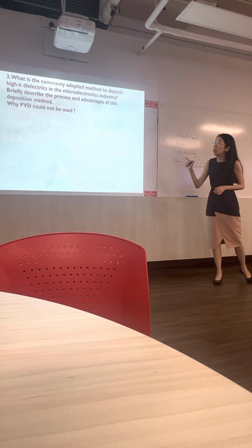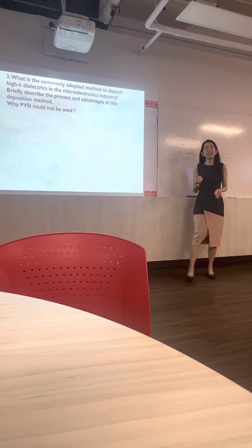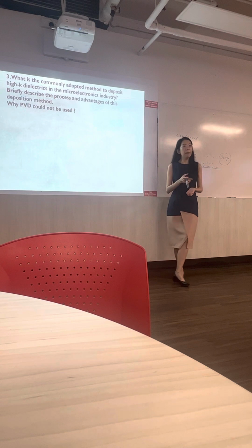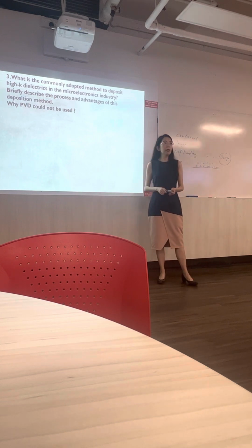So why can PVD not be used? Actually it can, I told you. PVD can deposit. Evaporator is a good method. Sputtering is a good method. If you Google, there are many researchers using these methods to evaluate high-K candidates. But in manufacturing, it cannot. So why? Not as conformal, line of sight deposition.